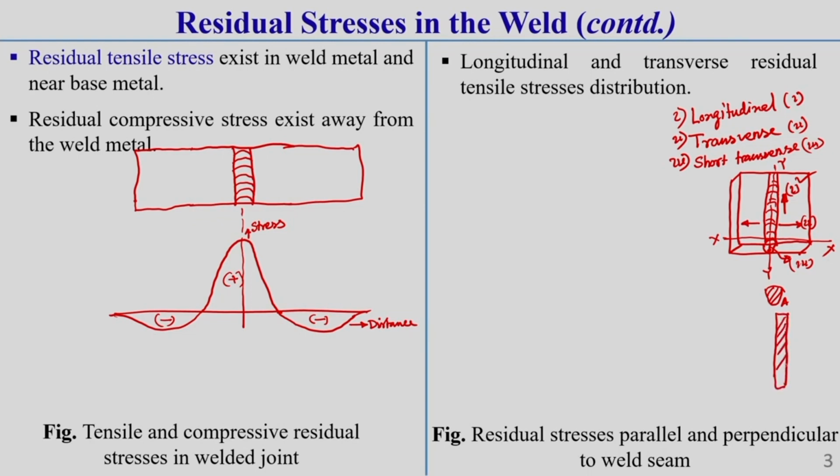If we compare in this way, in the welding direction, the cross section which is supporting this shrinkage type of force, or you can say the restoring force, is along the transverse direction for the transverse residual stress. I am representing the longitudinal cross section as A1, and the transverse cross section as A2.